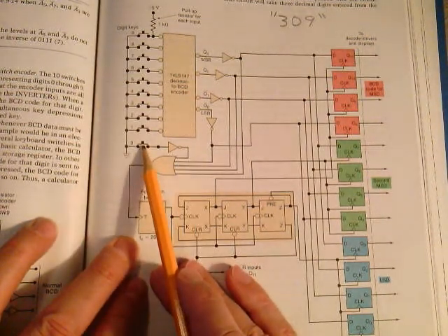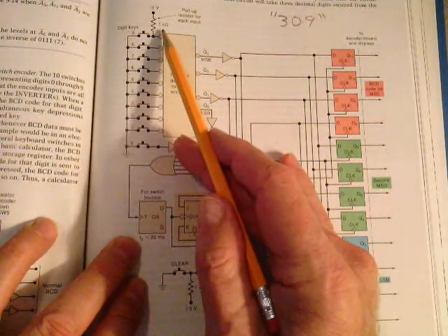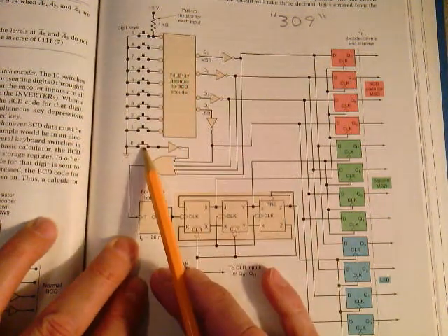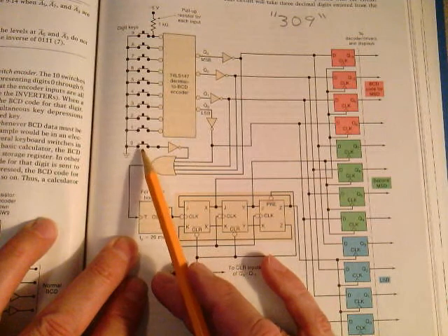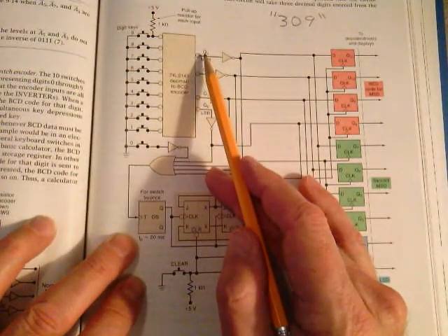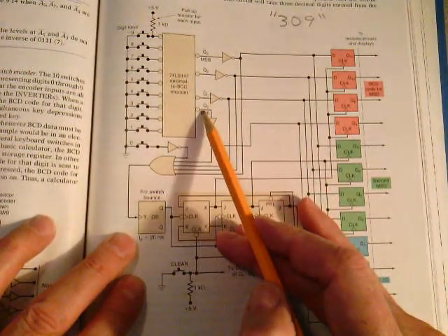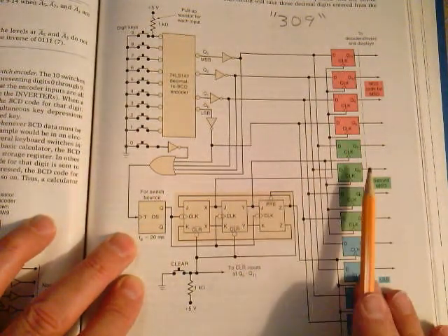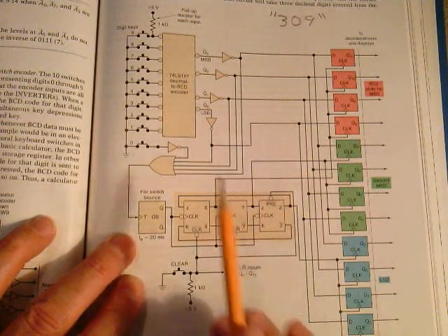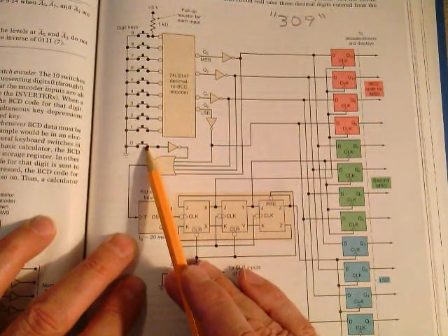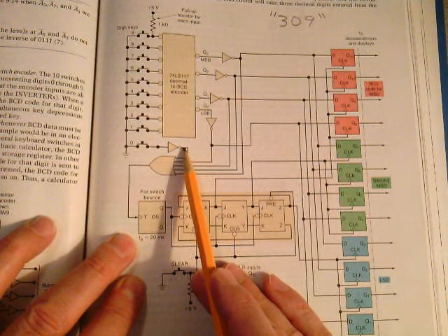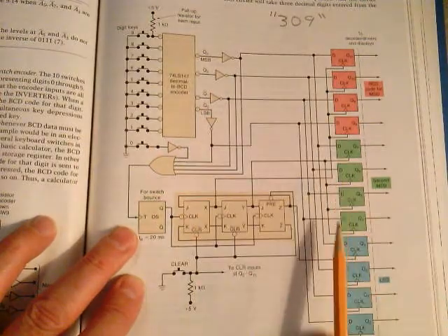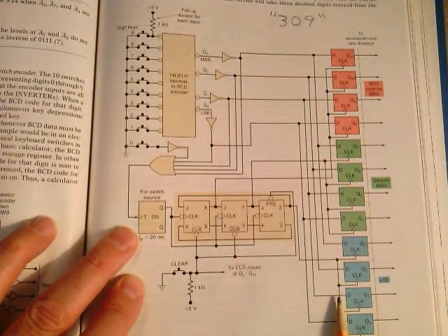What's next? You push 0. When you push 0 here, none of this is active here. None of this is active because this button's down here. So you push this to 0 right here, and this stays at a 1, 1, 1, 1. That puts a 0, 0, 0, 0 out here. So 0 gets set up here, 0 gets set up here, 0 gets set up here. But that 0, when you push it, it makes that go to a 1 out here. That is going to fire that one shot. So that 0 all gets set up, all the transients die out.